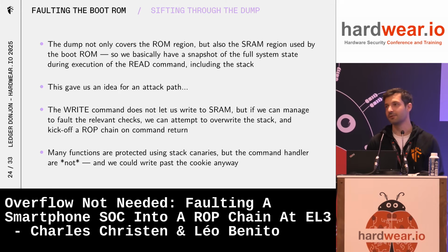You may think of stack canaries for that, but as it turns out, the command handlers are not using stack canaries. And this is not a linear overflow like you have in software. So actually we could just write past the stack canary. You don't even have to dump it or anything.